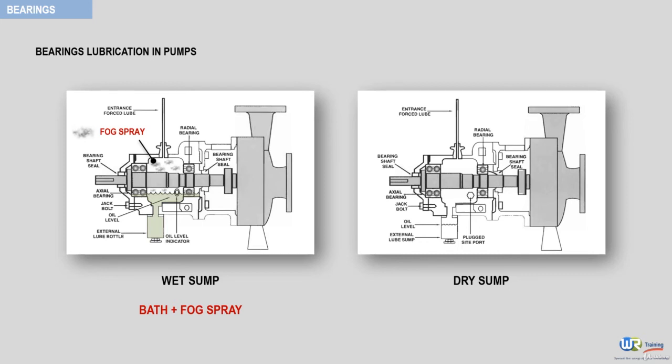The dry sump method of oil misting has no liquid oil contained in the bearing chamber, but instead the entire chamber is filled with the atomized oil fog, as depicted in the figure. Both the dry sump and wet sump methods of oil misting have a slight positive pressure in the bearing housing. This prevents contaminants and even humid air from entering the bearing chamber.